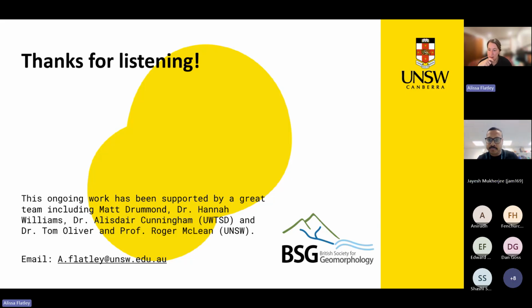At the moment, I've been doing some alignment with some ground control points and some benchmarks. For targets, it just so happens that I've got a few, and I wasn't planning this. I'm actually just using these stickers. So these are just the little targets. They're similar to the larger targets that you would stake down. These targets just came with the handheld TLS that I purchased, but I do have plans to mount them onto a board that I can then peg into the ground so that they don't fly away. I hope that answers your question, but if not, feel free to email me.